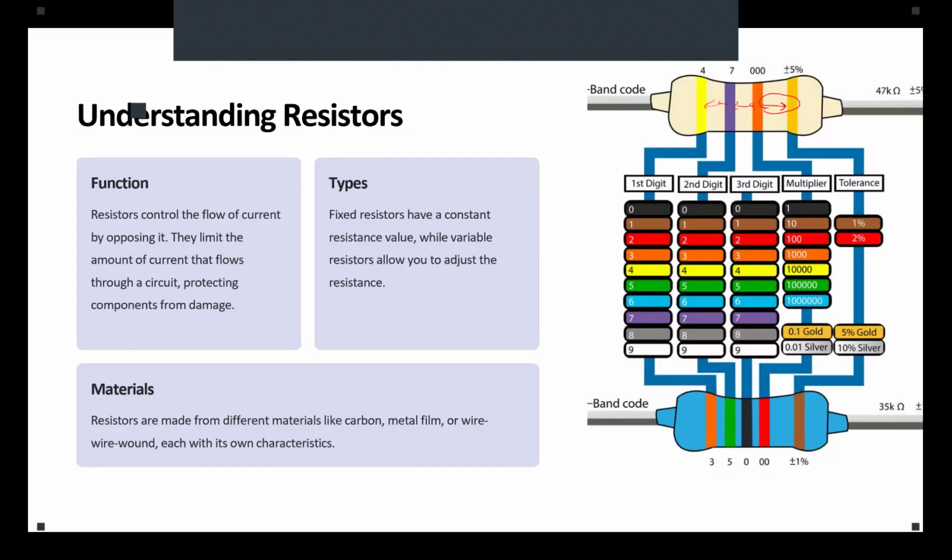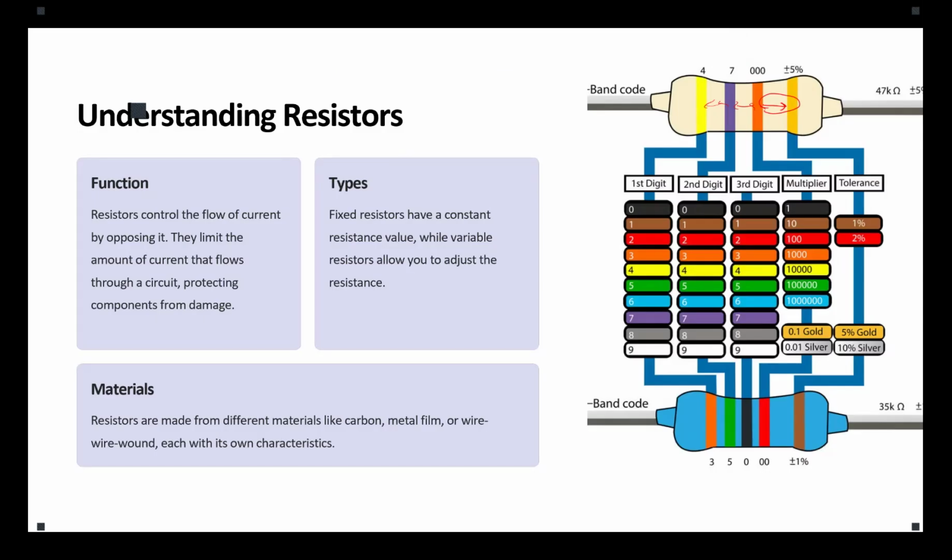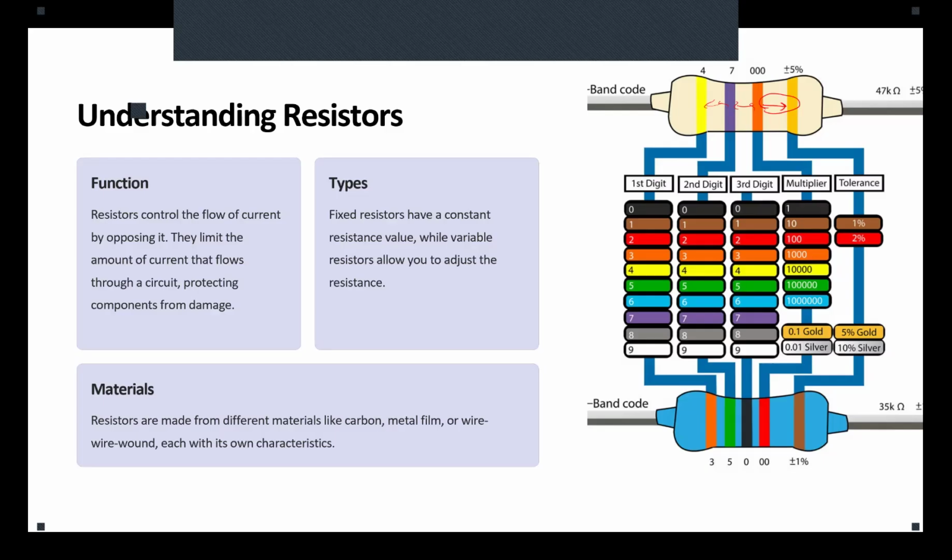Are we good? Now, when you look at the resistor and have your tolerance band at the right side, there will be either 2 or 3 lines that represent digits: the first one, the second one, and the third one. Another band follows those 2 or 3 digits, which we call the multiplier. Those digit bands are numbers, exactly whatever code you have. If you have black, it's 0. Brown is 1. Red is 2.